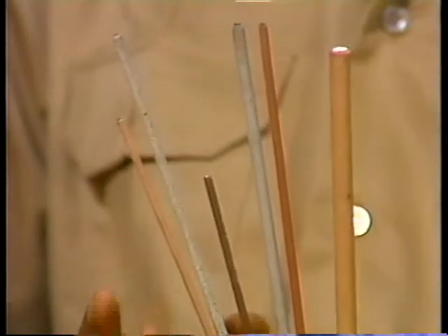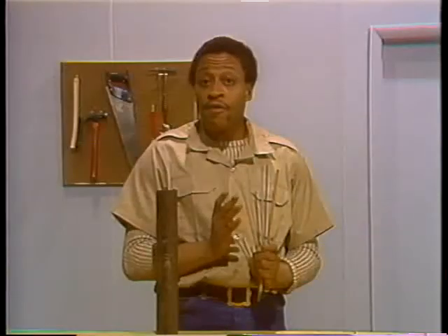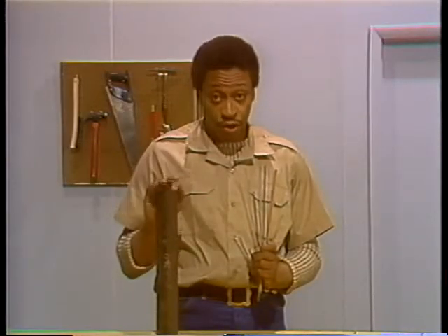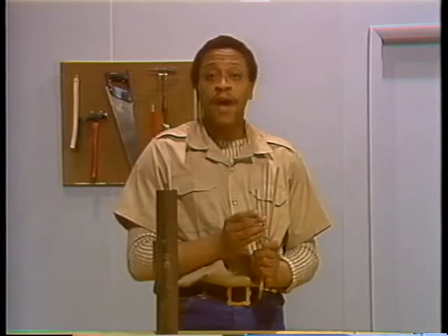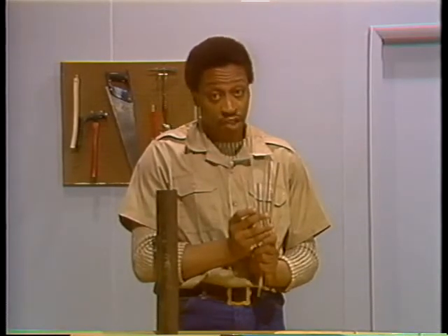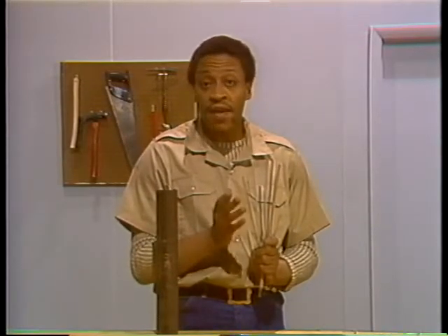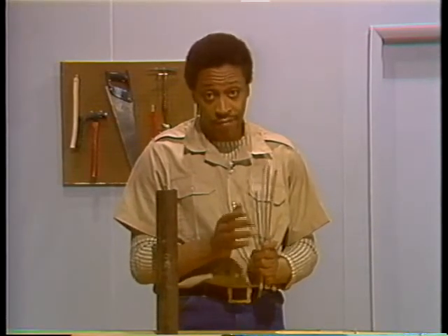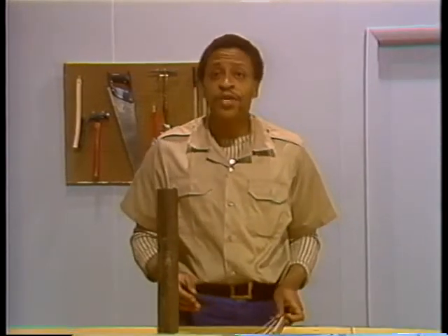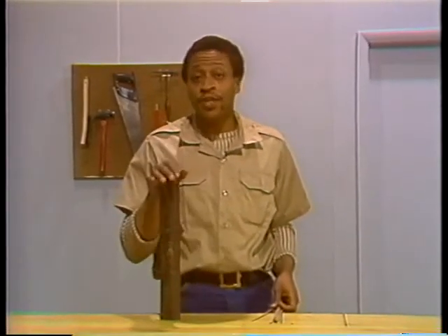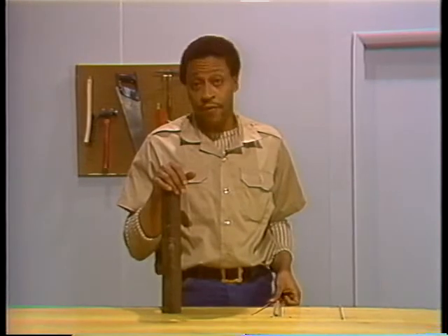There are a lot of different kinds of weld rod available, and there are a variety of metals used in boiler tubes. The type of tube metal and the type of weld rod must be compatible. If the wrong kind of rod is used, the weld made with it is very likely to fail. For this reason, the foreman or an experienced welder usually chooses the type of welding rod.